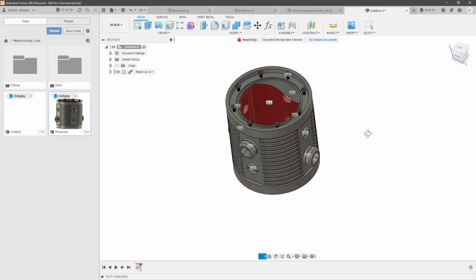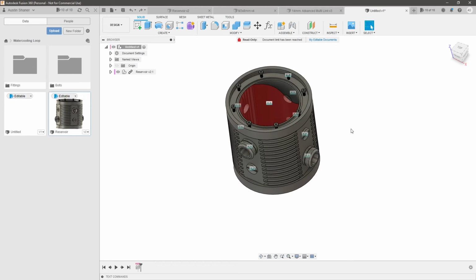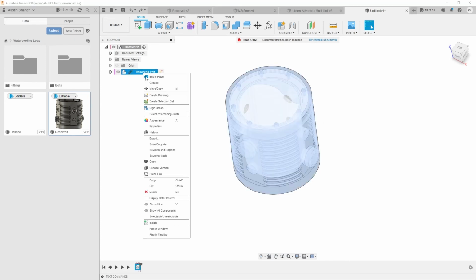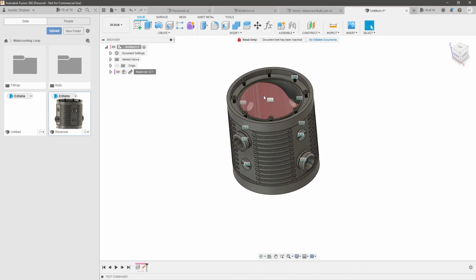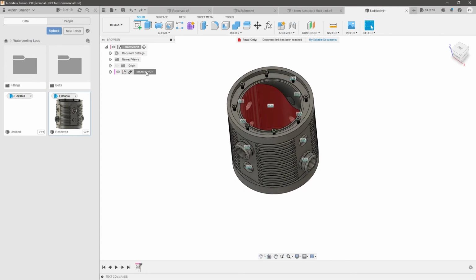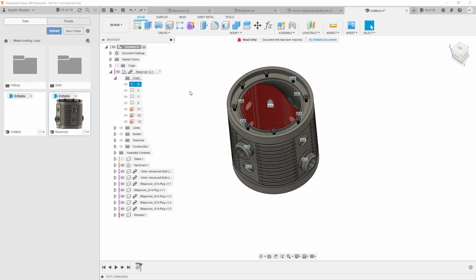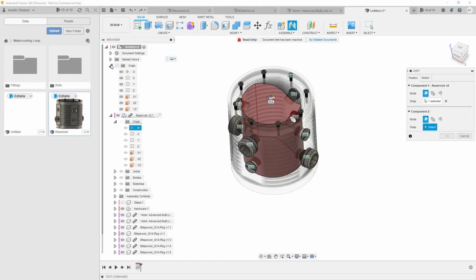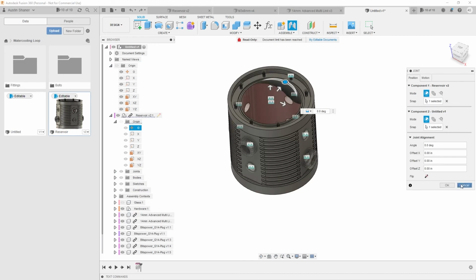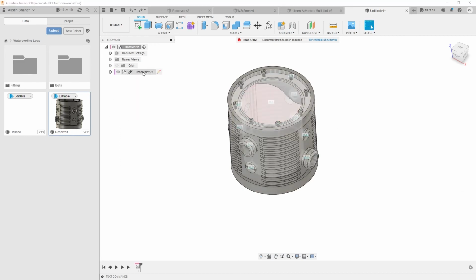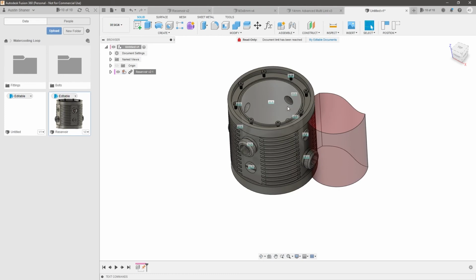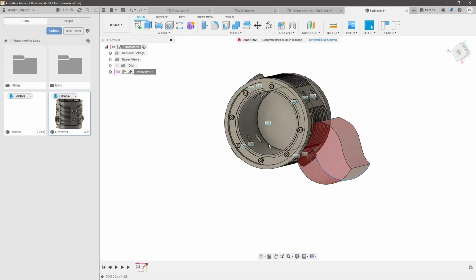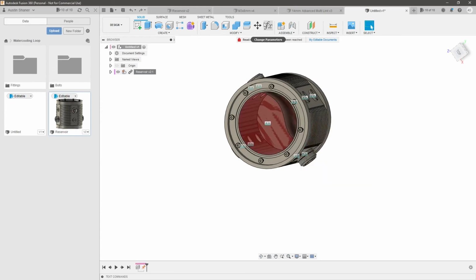It's very good practice when you're building an assembly like this of multiple subcomponents, or sorry, subassemblies or parts, the very first one in the top of your tree should be grounded. What that does is it effectively joins it to the origin point of wherever it currently sits. Another way to do this is you could open up your origin point right here, and you could join that to the origin point of your design and effectively do the same thing. But ground is a very lightweight way, calculation-wise, to do that. So now this can't move. Well, this one can because we didn't join it. So let's join those. Actually, we need to join that in the other design.